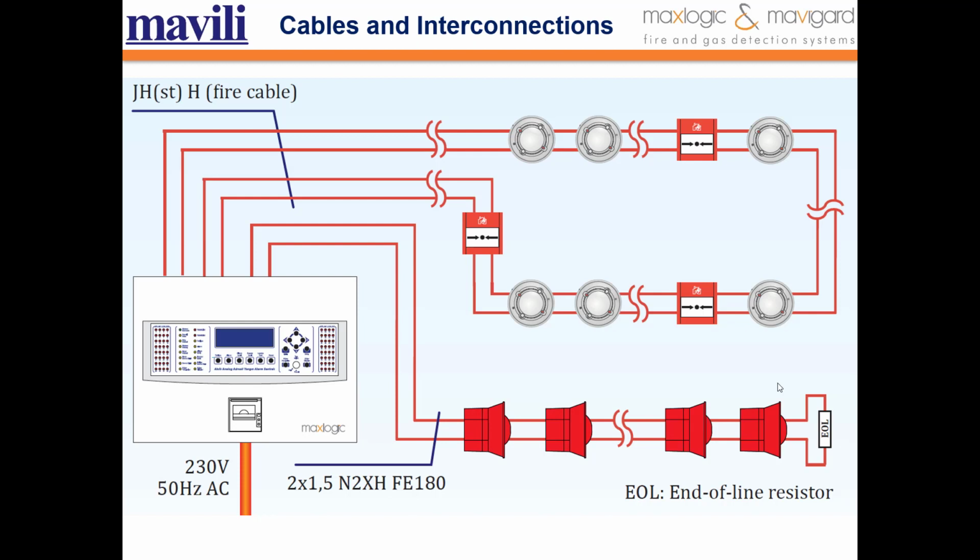As you can see, this is cables and interconnections of fire alarm system. The cables that need to work for 1 more minute after the fire is detected must be resistant to fire and firefighting for at least 30 minutes or must be reinforced to withstand this time. These cables may include connections between the control and display equipment with separate power supply, alarm devices, power supplies including links between them. Connections between the separated parts of the control and indicating equipment.